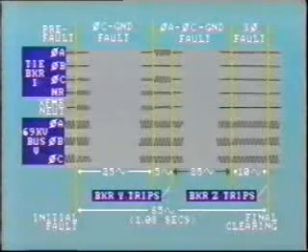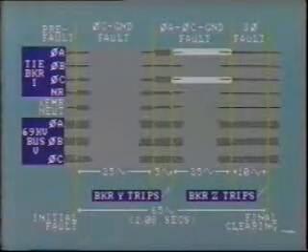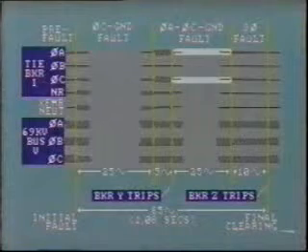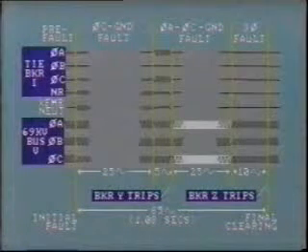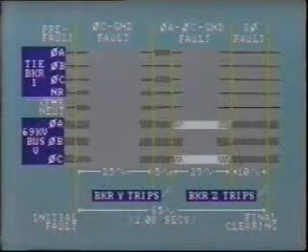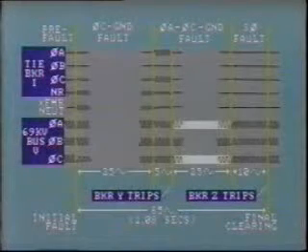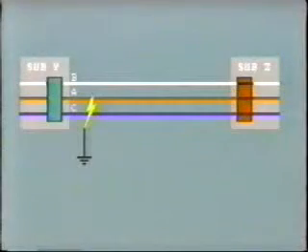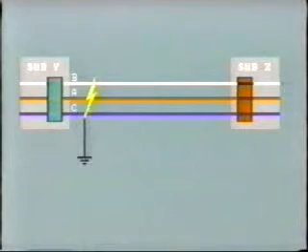For the next 25 cycles, we still have a double line-to-ground fault, but the current magnitudes are very much reduced because one end of the line is open. You can see that the A and C phase bus voltages are back to near normal. At this point, the fault again changes. The A phase conductor now burns open. The tree contacts B phase and falls to the ground. But all 3 open conductors are now in contact with ground, resulting in a 3-phase to ground fault.